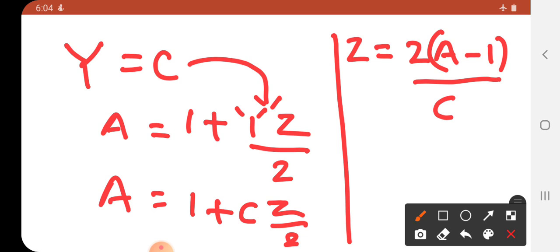Okay. So if the value of Z is real and imaginary, the real term corresponds to the resistance and the imaginary term corresponds to the reactance. And if we know the frequency, then we can easily find out the series inductance of the line. Yes, this is like this.